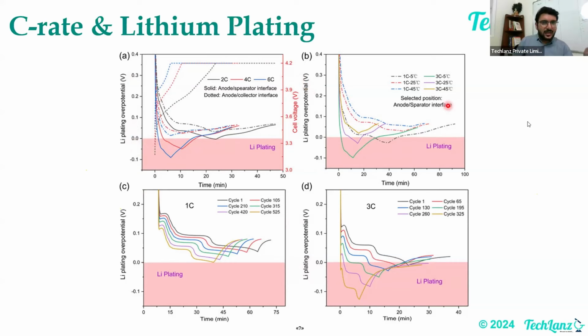This is something very, very important, because charging algorithms are generally not taken care of by the battery people. There's a charger team that sometimes provides it. But if they're not working together as a team, there is no collaboration. The charging team will say, I want to fast charge the battery pack, or the product planning team will say, I want to implement a 150 or 250 kilowatt charging system. But what will happen if you haven't considered these scenarios in your simulation in advance? Eventually, when your battery is old, after some time, maybe 2 years, 3 years down the line, thermal runaway scenarios will happen